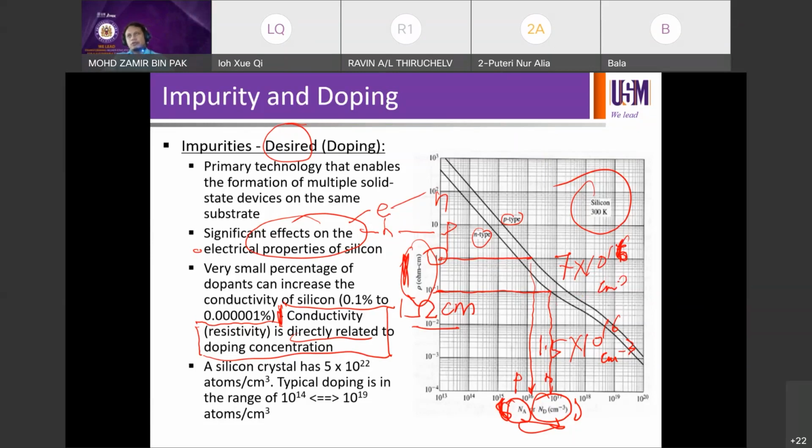So when you work on a silicon wafer, you don't have to really know the level of the doping concentration just yet. You can just tell by looking at the label on the cassette before you take the wafers, right? From there, you can come to this curve, because this curve is what we call the reference, the gold standard for resistivity against the doping level for p-type and n-type wafers. Okay, so then if you want to go into the lab and do the measurement and characterization with Hall effect and so on to really measure the actual dopant concentration, you can do that as well. But you already know from the resistivity curve to begin with, right?